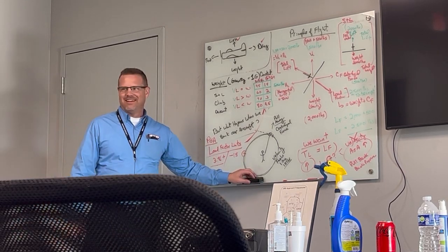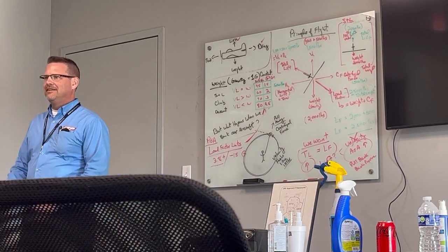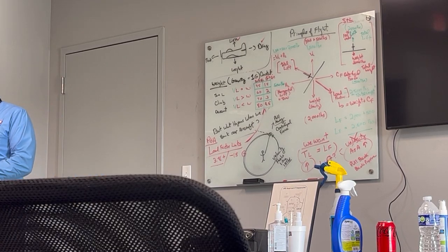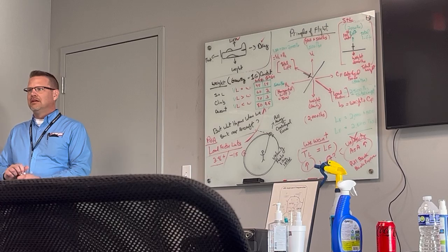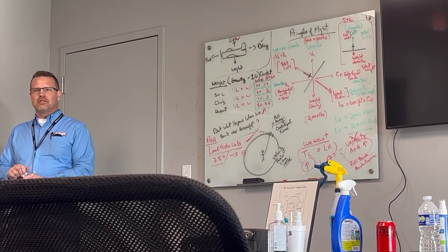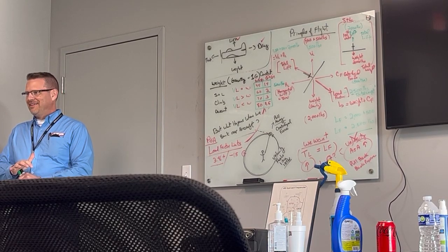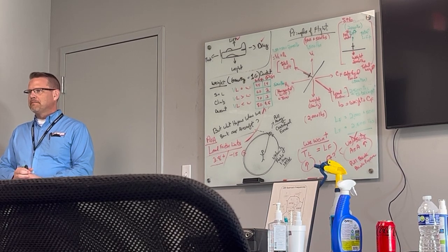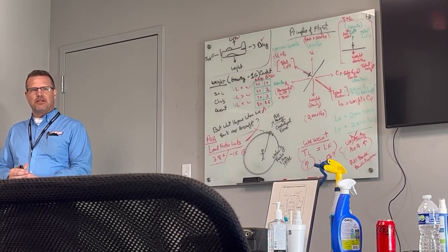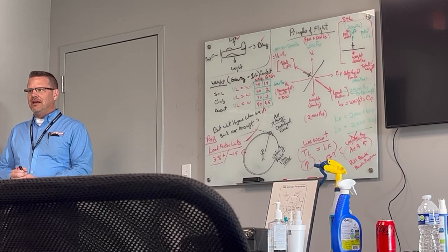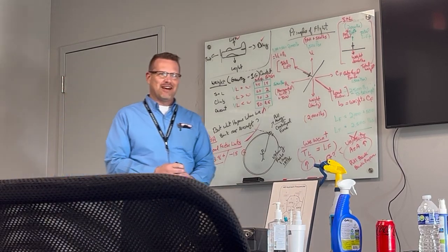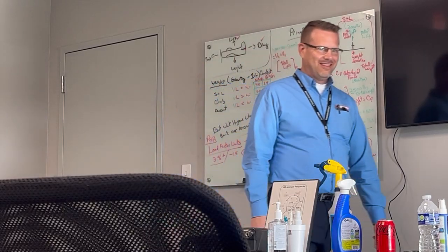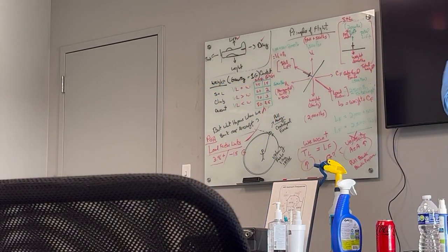It's probably the same thing, but just for the G500 Archer, it's not approved for a negative load factor limit. So do we even mention it then? Well, and again, we had this discussion the other day. That's what I was gonna ask, would you put 0 then, and then 3.8, because it has the positive, it just doesn't have a negative. It did in the POH though. That was just for the G1000. We figured it out. Oh, is that what it was? It was a G500 versus a G1000? Yeah, I showed you the G1000 and it has the negative 1.5, but those don't.